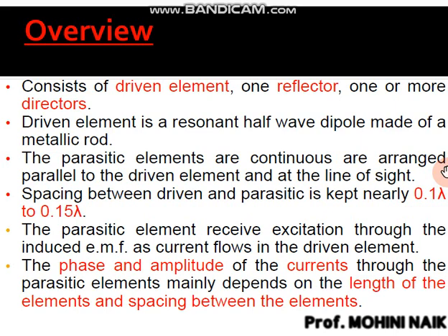Now what is the spacing between the driven and the parasitic element? It is kept nearly between 0.1 lambda to 0.15 lambda. So it is always in relation with your wavelength. Suppose, as I told you, I want to design a television transmission, and 35 megahertz is the frequency. I will have to calculate its wavelength and then find the spacing.